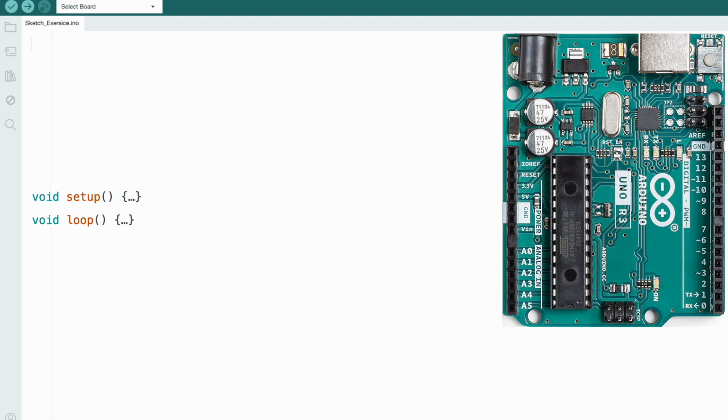So we have this LED 2, and you'll notice that the variable itself is declared as an int and not a const int. That's because we're going to use this LED variable throughout the program, and we're going to increment it as we want to step through the various LED pins that we want to write out to.